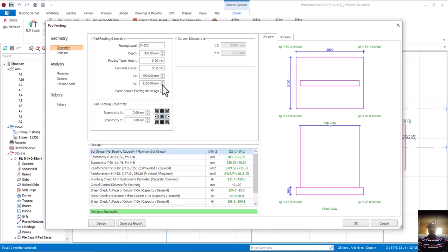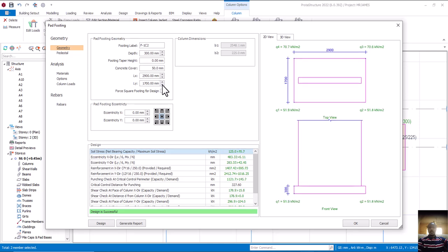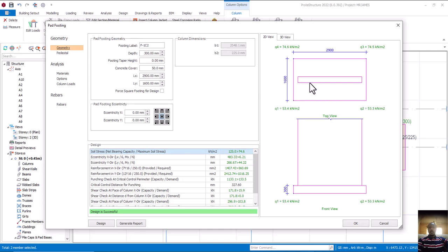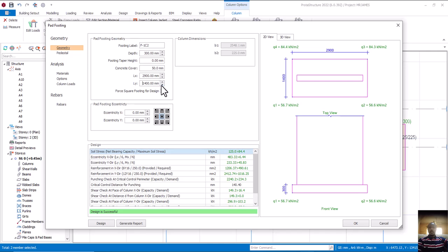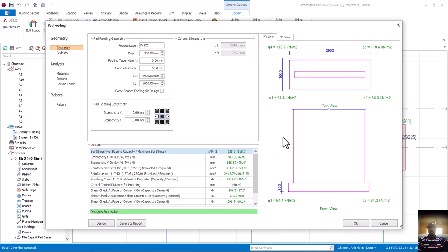So that at least the cost will be minimal. I'm taking it to 1000 plus. Yes, it's passing, because our column is along this line, one around here and one around here, so the space here is enough to distribute the load. Even 1000 passed my design instead of 2900. These are the settings adjustments you need to do for your foundation design.